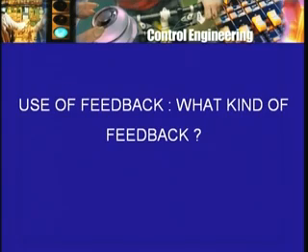So that's one thing. The other is the load torque, uncertainty about the load torque. If it cannot be ensured that you know TL, what it is going to be, these two things will necessitate the use of feedback.